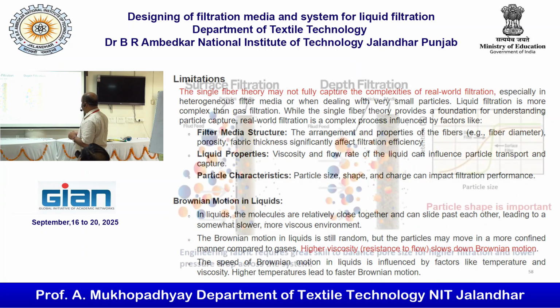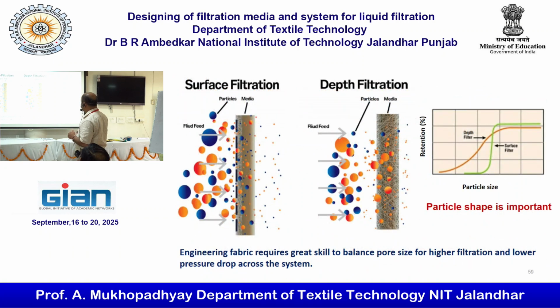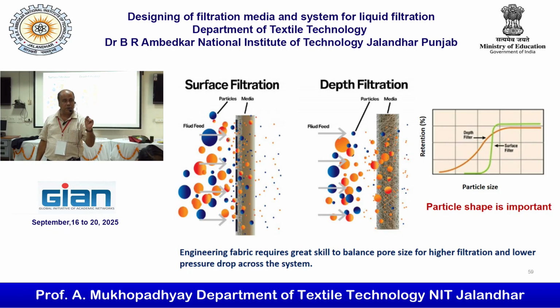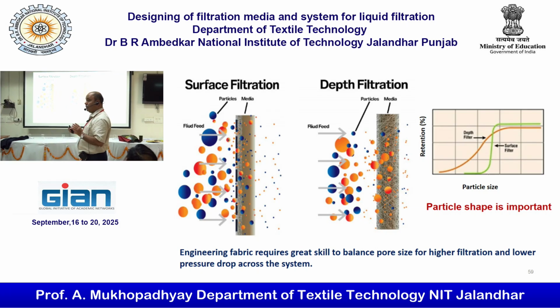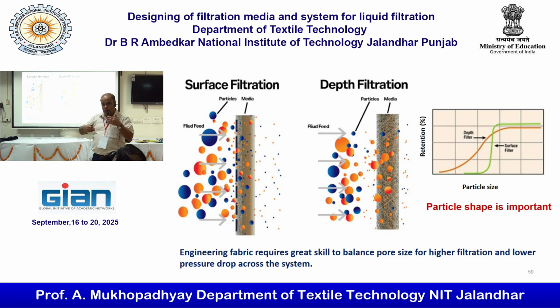Now here is the concept of surface filtration and depth filtration. Surface filtration will be on the surface. Whenever I say surface filtration, it is not that you will get 100% surface filtration. To a certain extent, depth filtration is inevitable. Again, whenever we go for depth filtration, there is a certain amount of surface filtration. This is the philosophy, and according to that we make the material. If I have shown you a surface filter media, that doesn't mean it is giving you 100% surface filtration. That's why clogging is there, and that's why life is a big concern, because some amount of depth filtration will be inevitable.